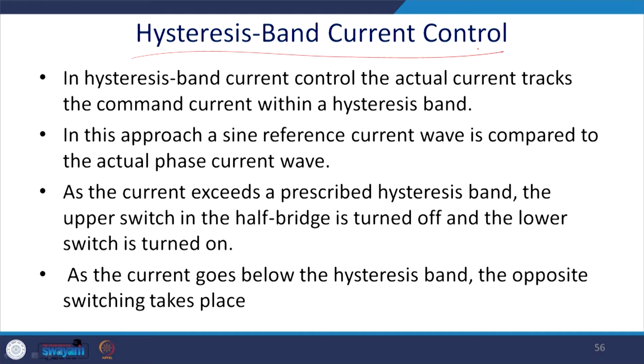In hysteresis band, this is all the current control technique. In the current control, the actual current tracks the commanded current within a hysteresis band. This hysteresis band can be a proportional band, or it can be an algebraic band, or you can have a constant band.